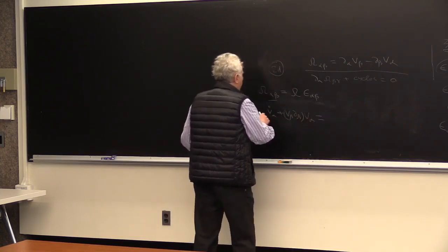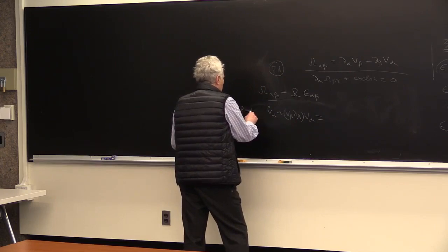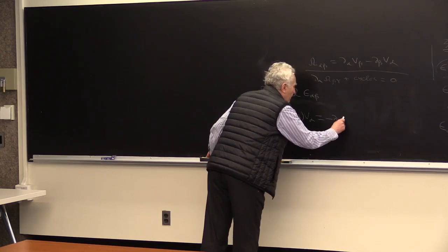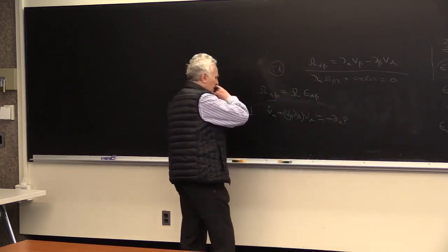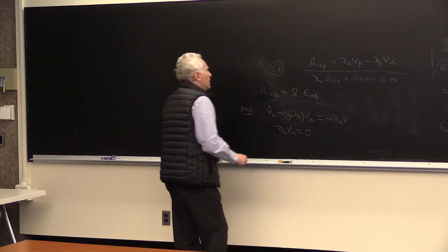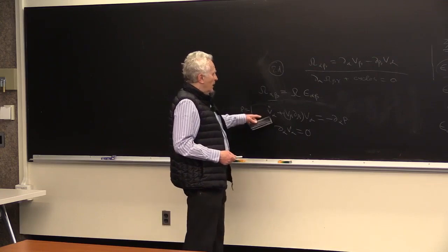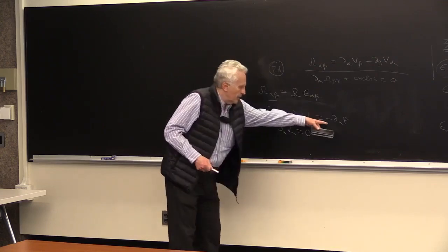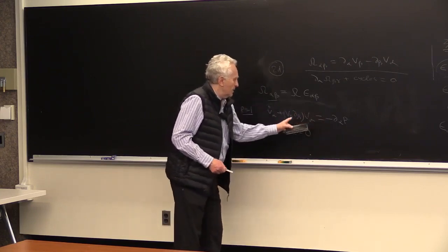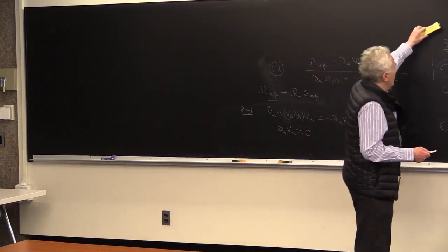I looked at incompressible fluid. The pressure is defined from d alpha v alpha equal to 0. And as we said many times, if we differentiate it, take divergence, and so on, then we get pressure explicitly in terms of the velocity for incompressible fluid.